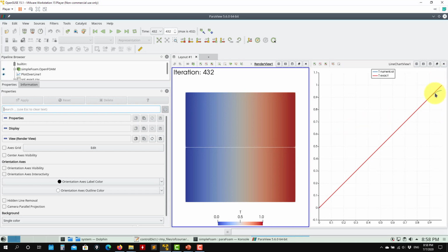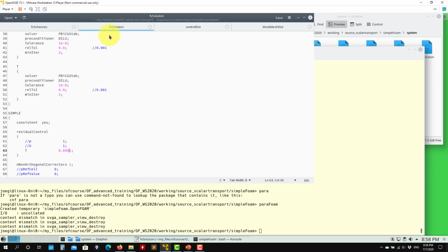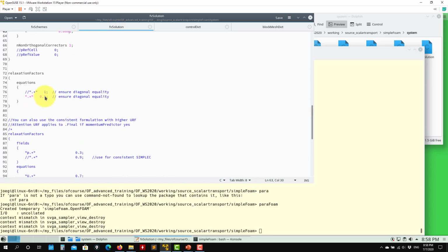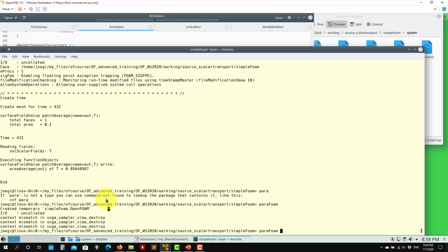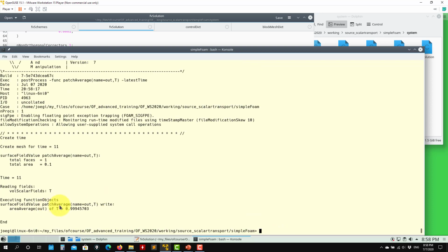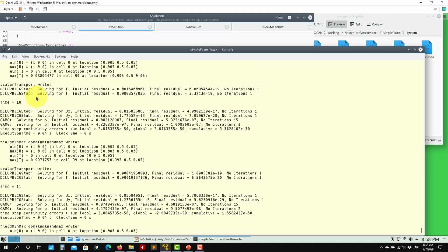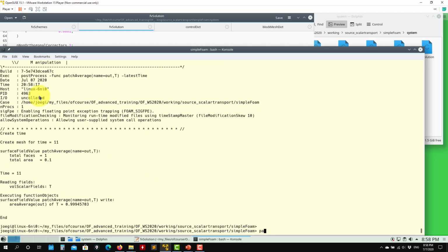And boom, it's arrived there, and you need just to go a little bit more. What we can do is just to increase this one. So if I go here 0.7, or let me go 0.9, we are going to go fast and furious. See that just 11 iterations were there. You monitor your solution, there are no oscillations, and we're ready to go. We're okay.